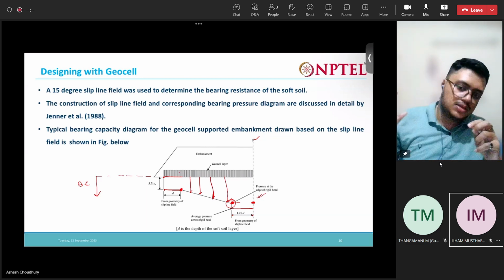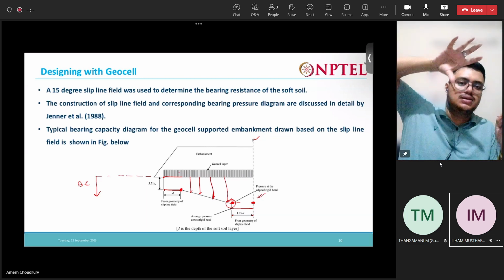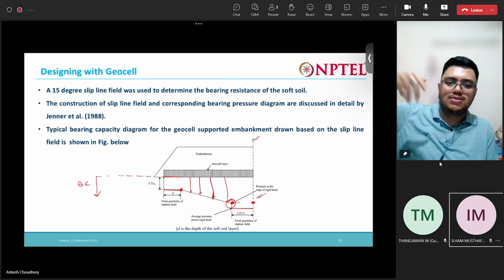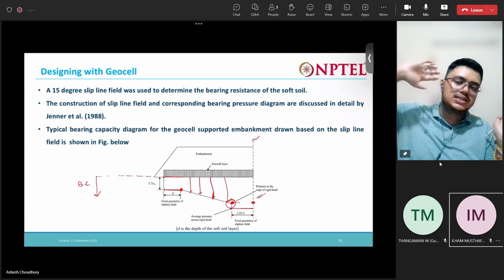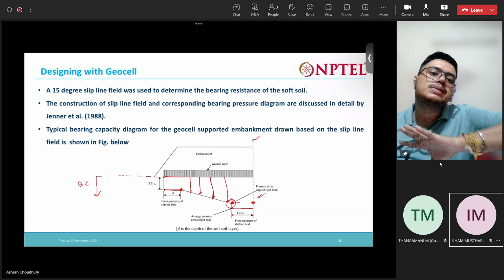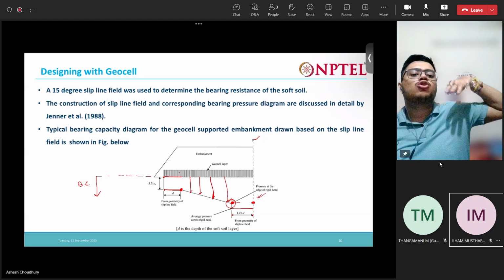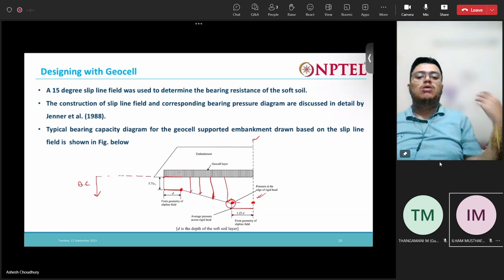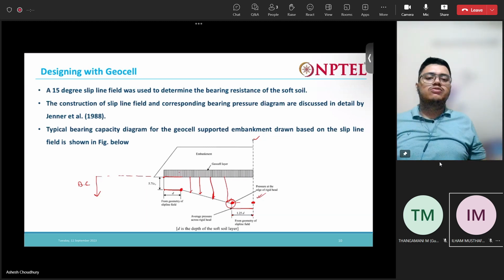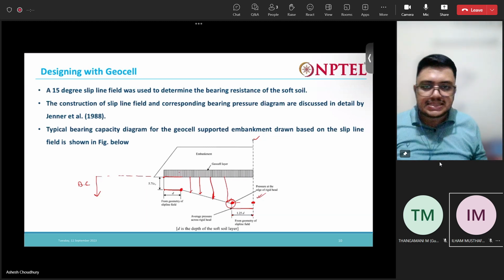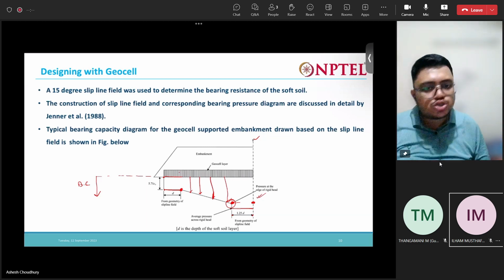All right, the limit is increasing in somewhat sense. You can think of it in that way, that the limit is increasing. Initially, what is the normal soil? For normal soil, what is the elastic limit? It's 5.71 C. This is the elastic limit for a normal unreinforced soil.